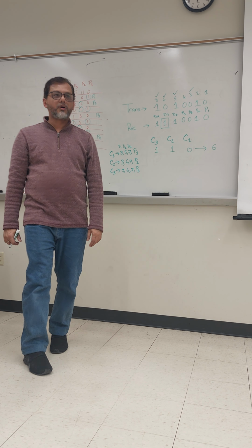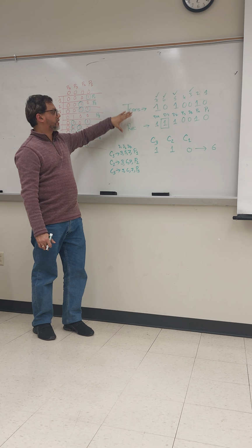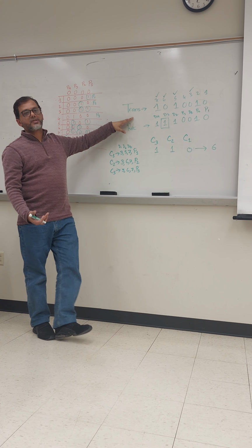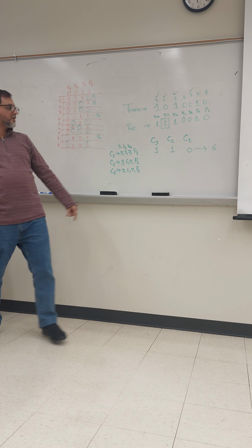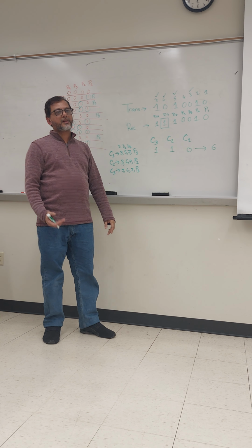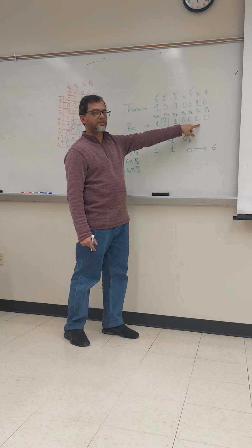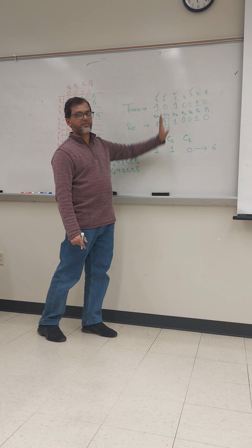Okay. So again, I'm repeating here. This data is sent to us, and this data is received. We need to check on the receiving side, and the checker is known as the parity checker. As we have a 3-bit parity, we have a 3-bit parity checker: C1, C2, and C3. C1 corresponds to positions 3, 5, 7, including P1. For parity checker C2, it corresponds to 3, 6, 7, including P2. Parity checker 3 includes 5, 6, 7, including P3.